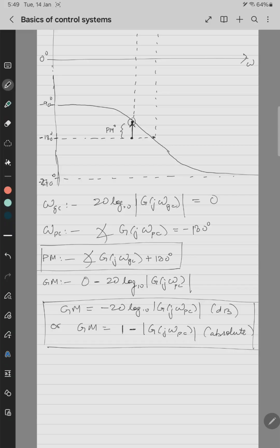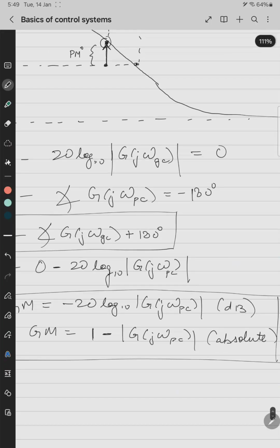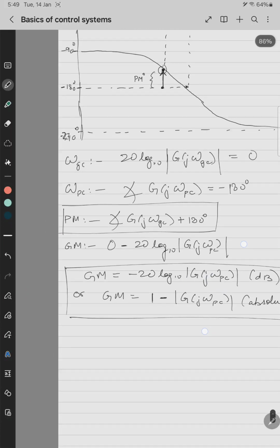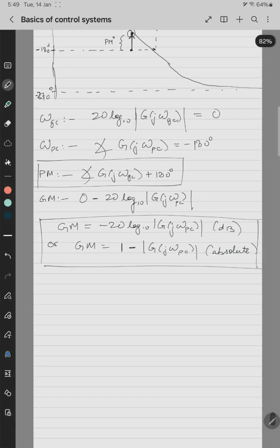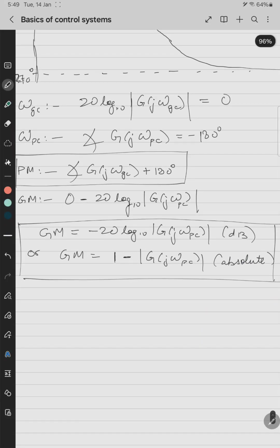Okay, so gain margin is this much is the margin, meaning this much gain you can add in decibel. And what is the thing that adds the gain? A controller adds the gain. So D of j omega should add that gain at omega pc. Similarly, phase margin is the angle of D of j omega. What should that be? That is the maximum of this.